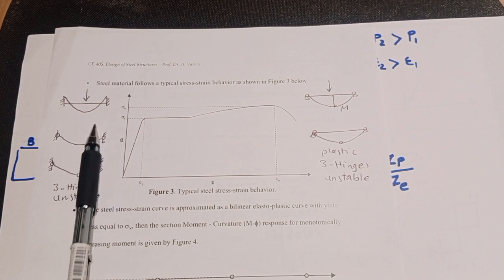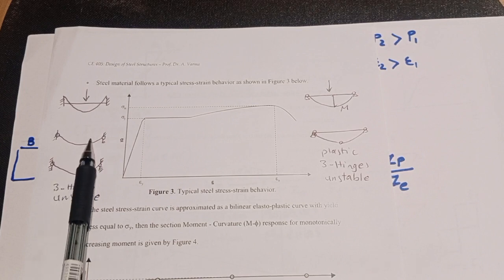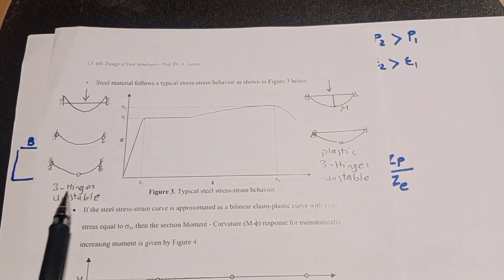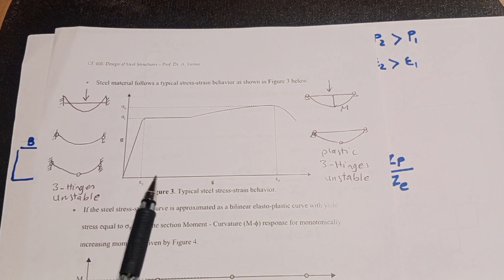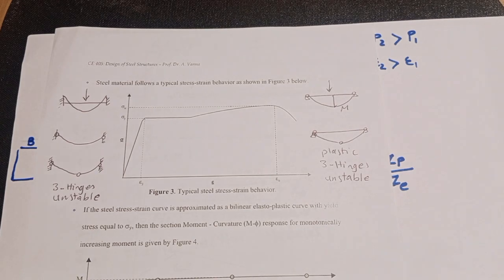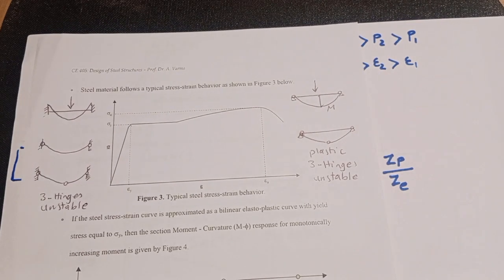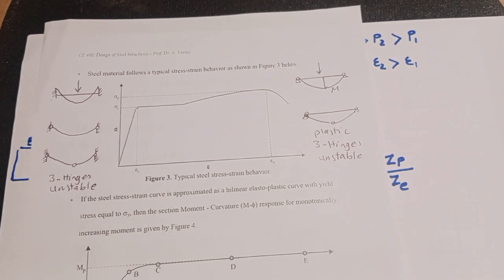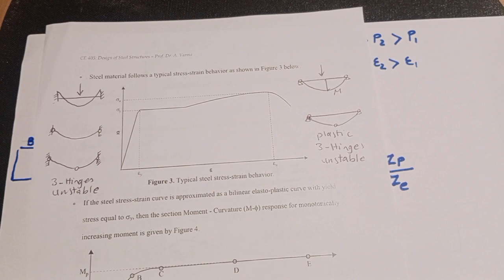And if we increase the load, the third point that has the maximum bending moment now reaches the collapse point or fail point, and we have three hinges, 1, 2, 3, three hinges in one row, and the section is unstable. So the load causing all these three hinges to appear in the structure is called the load that's causing plastic bending moment, and it is the maximum yield strength in plastic, and it normally gives better capacity of the structure.